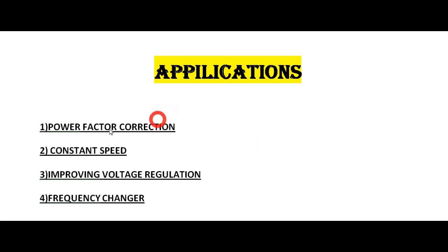As I said, the synchronous condensers. What do you mean by synchronous condensers? A synchronous motor operating at no load with over excitation and supplying leading reactive power is called a synchronous condenser. It is used for improving the power factor of industrial plants, mainly for lagging loads.